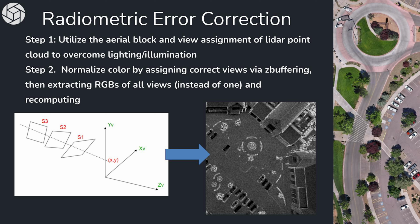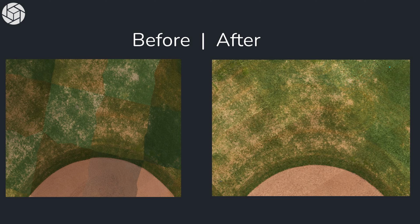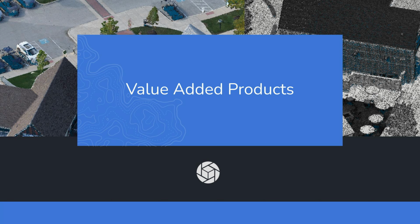So once we do that, we normalize the color of all cameras that are viewing that specific LiDAR point, and generate a much more unified radiometric colorization. So here's what that looks like before and after, and again, before and after. Again, we're just leveraging the strength of the bundle block adjustment.